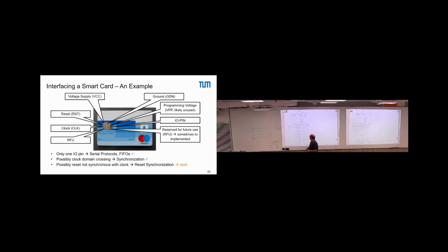You have here the reset signal, right? The reset signal in an ideal world would arrive on all the points at the same time. Yeah? So if we release the reset here, it would go up. If it goes up here, it should go up here and here and here, right? So in an ideal world, everything would go up here on the screen line. But now you have capacitances which delay your signal.